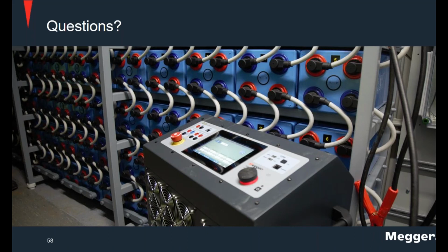So you have to have the appropriate connections, insulated tools, and obviously that equipment list cannot be 100% complete without talking about the safety side of things, right? The individuals involved with the test have to have the proper PPE and also a wash station. And we can even talk about ventilation in the battery room. So obviously PPE, all the tools necessary to do the proper connections for both the instrument, the DVMs, and in case of jumping out cells, and obviously the instruments themselves.